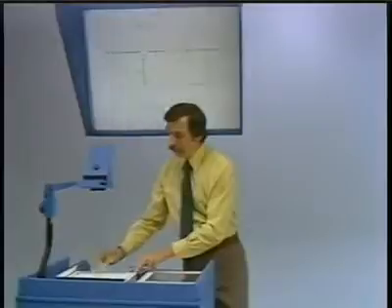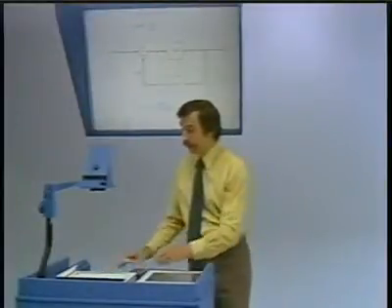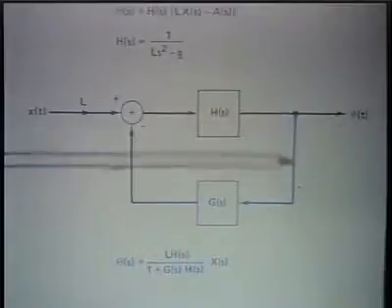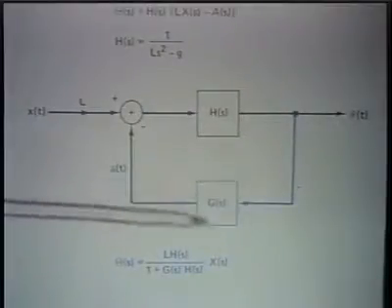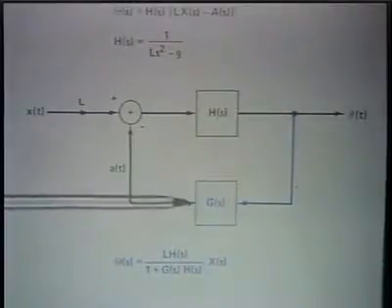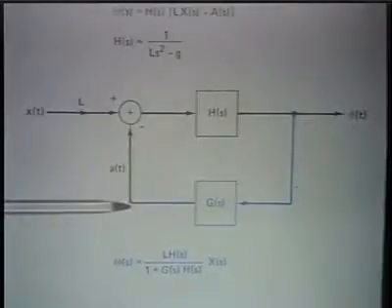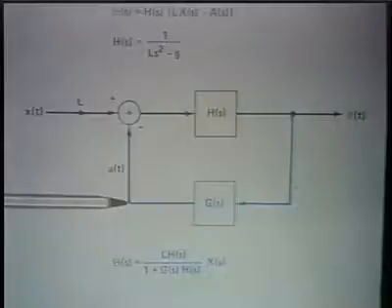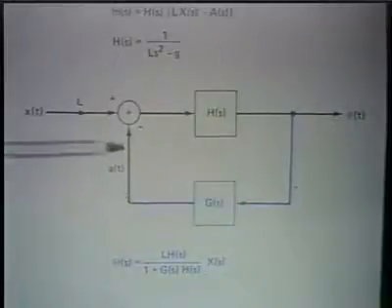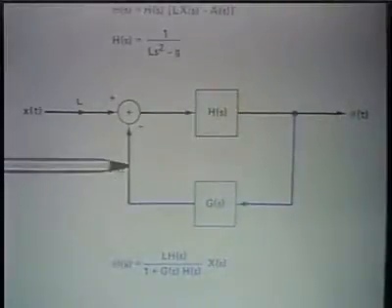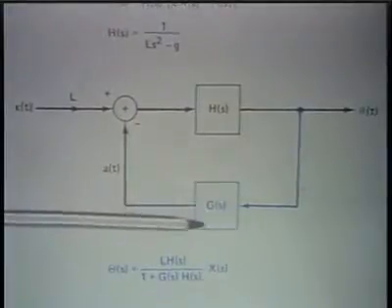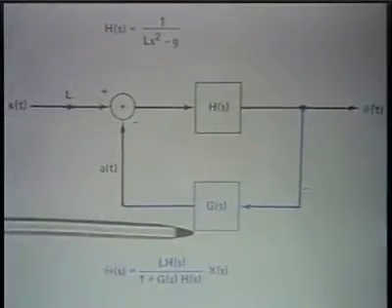So with feedback applied around the system, there would be some measurement of the angle through some appropriately chosen feedback dynamics, and that would determine the applied external acceleration corresponding to what the motor does by pulling the cable back and forth. And we would like to choose g of s so that the overall system is stable.